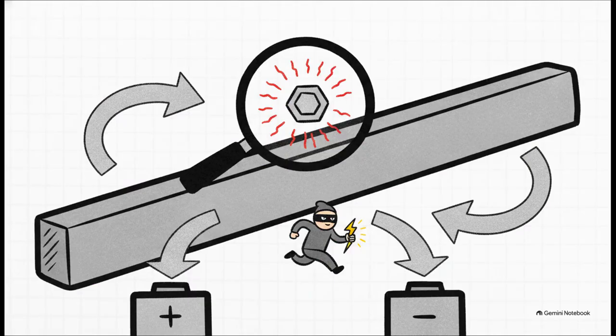So what's actually causing this? The primary physical culprits are essentially invisible thieves, parasitic contact resistances hiding in your high-voltage bus bars, your contactors, and your fuses. Think about it. During extreme acceleration or heavy regen braking, you have hundreds of amps surging through these nodes. Just a slightly loose bolt or a tiny bit of micro-oxidation creates milliohm-level resistance. And thanks to good old Ohm's law, that tiny resistance, when multiplied by those massive currents, creates a huge dynamic voltage drop. The independent sensor sees it, but the sequential AFE polling completely misses it.